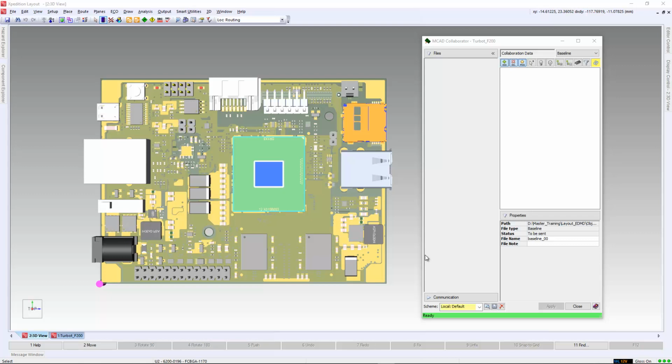Board geometry is typically owned and defined by the mechanical domain. It defines the thickness and the overall shape. However, the stackup is always owned by the electrical domain. In this example, we will show the process of sending the Xpedition Stackup data to import it into NX.